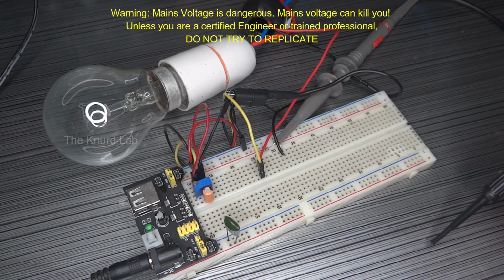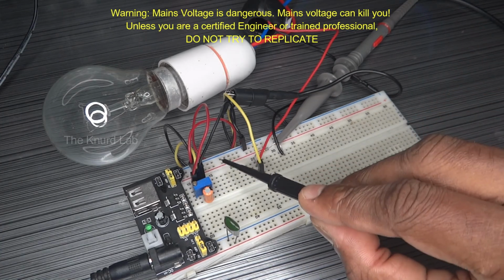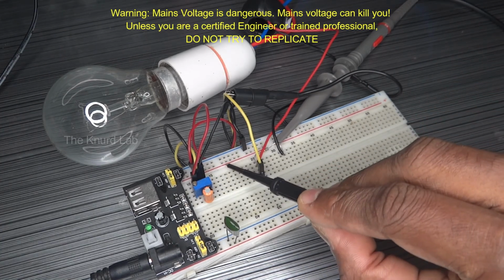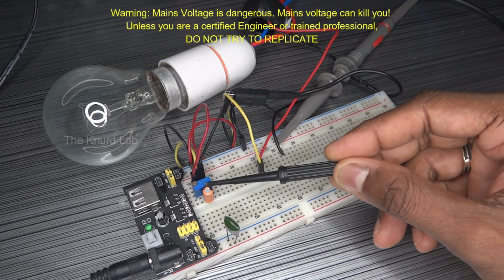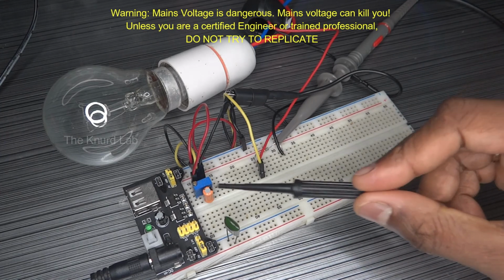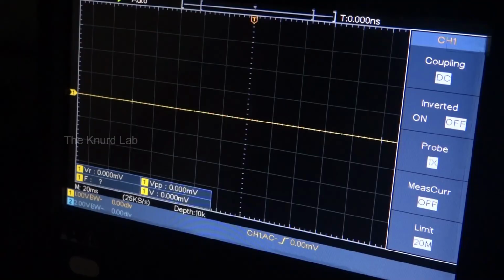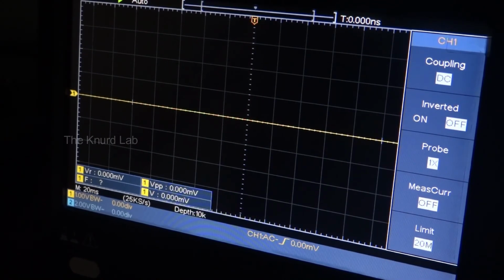To provide the 2.5 volt bias voltage, I have used a 100K potentiometer and adjusted it such that the wiper of the potentiometer outputs 2.5 volts. This forms the basic measurement circuit, and let's test the output using an oscilloscope by switching on the load. The oscilloscope is connected between the output of the burden resistor and the ground terminal.